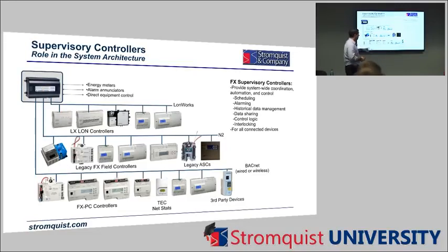So alarming. We talked about, to save you guys trips of running up however many flights of stairs or riding the elevator up to the 55th floor with your ladder, right? We can get an alarm. We can get that alarm sent to our smartphone, an email. It goes into an alarm portal where we have to acknowledge it to basically say, hey, I went and looked at it, this is what's going on, etc. All that's done at the Jace.